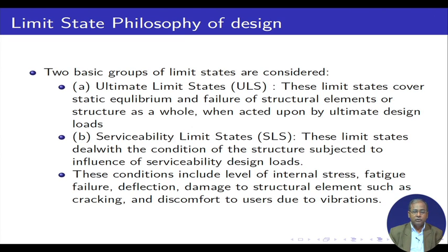Now, two basic groups of limit states are considered: ultimate limit states, or ULS. These limit states cover static equilibrium and failure of structural elements or structures as a whole when acted upon by ultimate design loads. And the second one is serviceability limit states, SLS. These limit states deal with the condition of the structure subject to the influence of serviceability design loads.